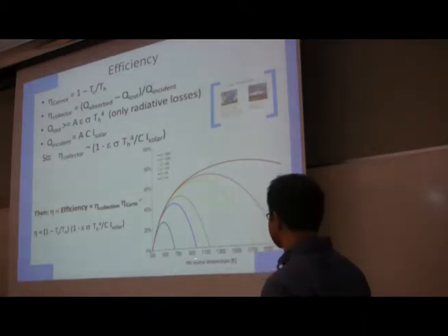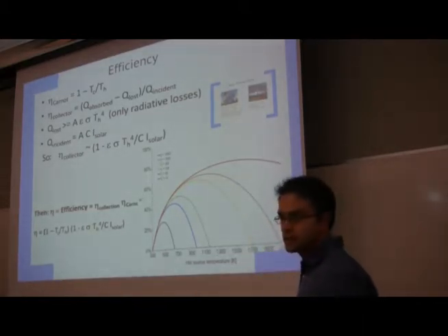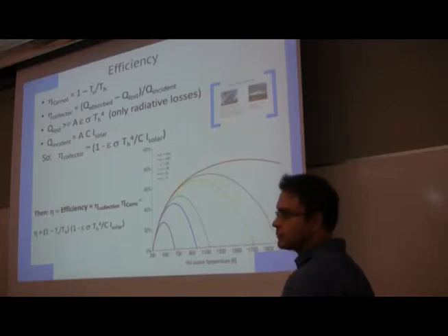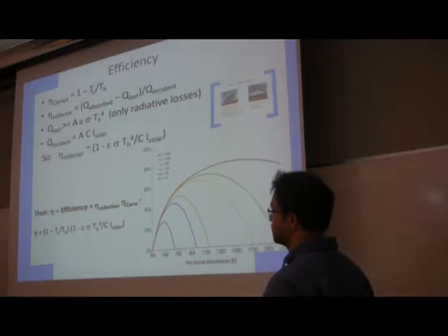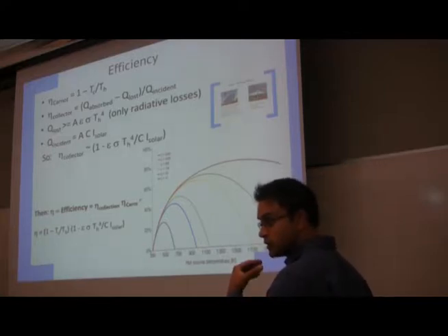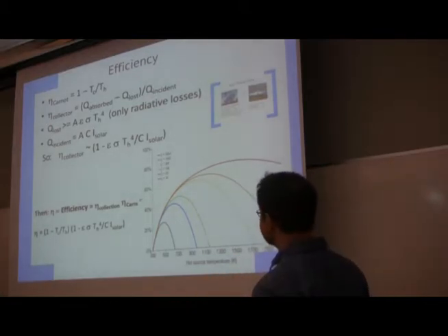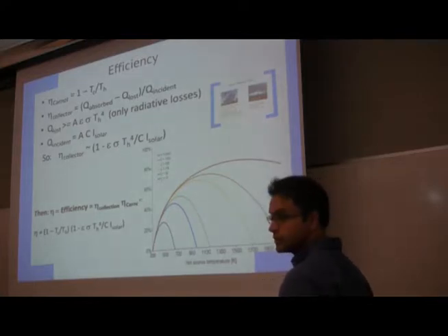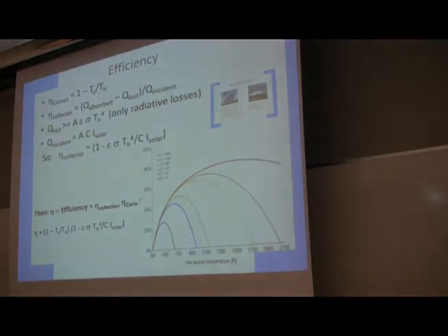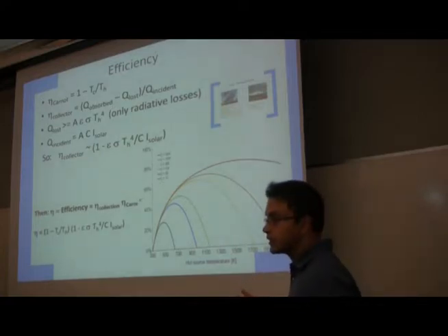So this is the hot source temperature, so this is whatever the collector is, right? You're heating it up with the sun, let's say. It doesn't need to be, but let's assume. And this is the efficiency with which the total system is working, heat engine and the collector, right? So you can see, C refers to concentration. The higher the concentration, clearly you're getting more sunlight concentrated into a smaller area. Your power density goes up, the temperature goes up. Right? Your TH goes up, which means that you will get higher efficiency.